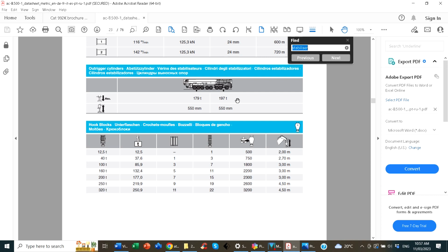So your ground conditions need to be able to support that. If you're actually on the ground, that can be fairly well determined. But I have seen a big crane go over because it was working on the top of a car park and the outriggers punched through the concrete of that floor. So you also need to consider outriggers and ground. But we'll move away from that at the moment.